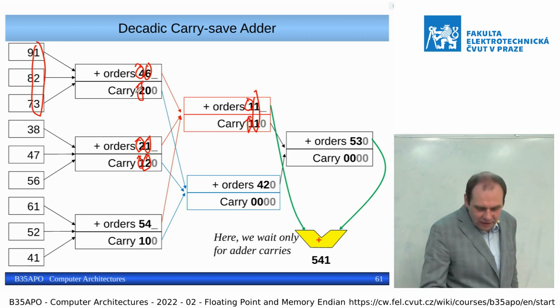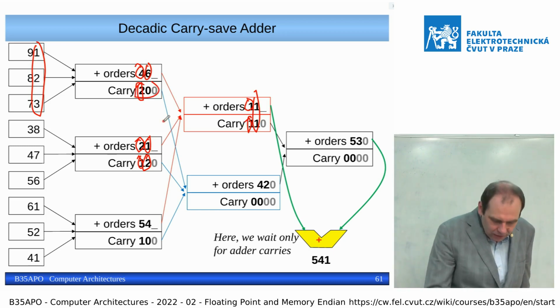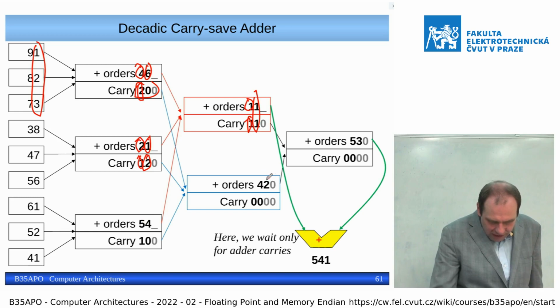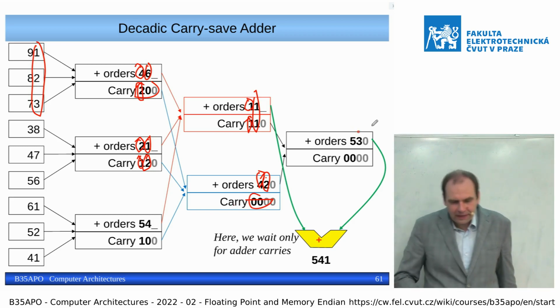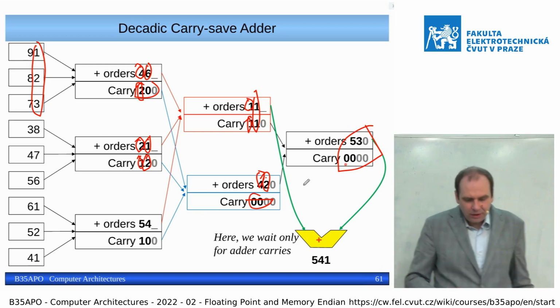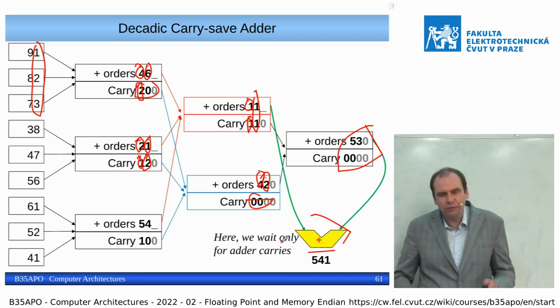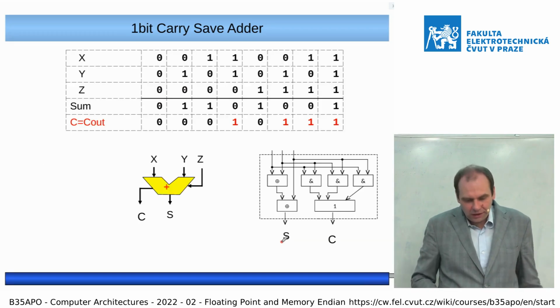And this way we have the results and the carry, which we have not counted into our sum, but we can do exactly the same with them, that we add only the corresponding digits in the decimal system to the result. And if there is an overflow, we have another carry out. And again, we can add the stuff this way. And only at the last step we need to add the carry outputs together with the actual value. So only once we need to build all that complicated carry propagation chain, which makes a problem.